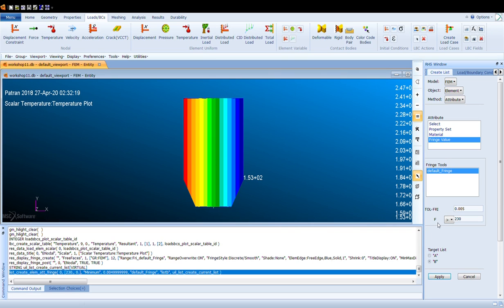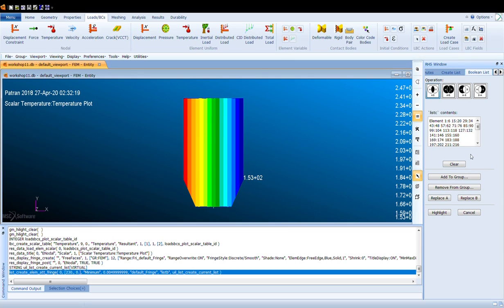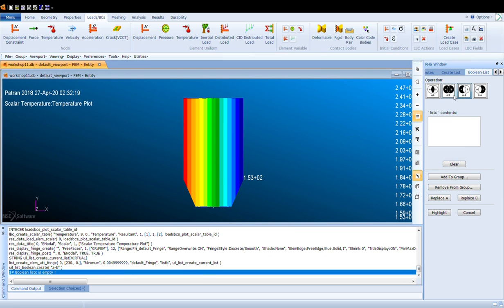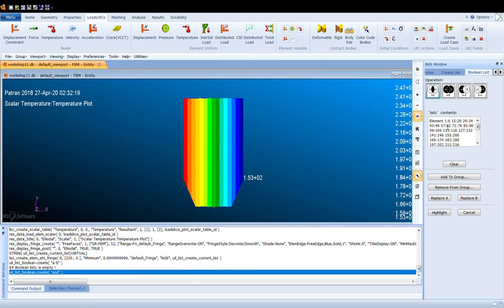So it got replaced. Now we're going to intersect it. So again, we go to Tools, List, Boolean. Once we are at Boolean, we're gonna hit again, intersect. If you want to make sure it did the correct ones, there we go.